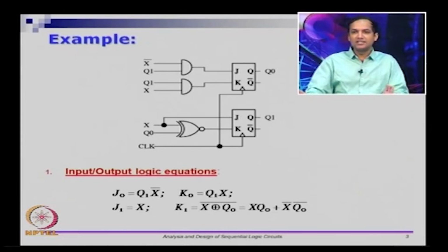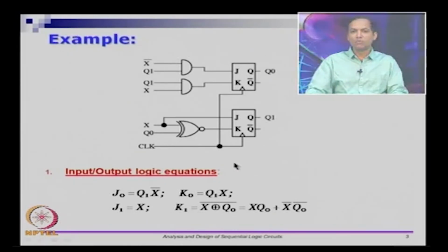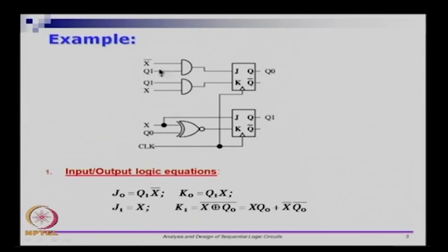So it is a valid synchronous sequential circuit, and from the canonical model, the only thing that has degenerated here is that there is no output logic explicitly, right. And to be more specific, since the output is Q1 Q0 explicitly, it is only the flip flops that are controlling the output. So this is actually a Moore machine. I mentioned this in the last video. This is actually a Moore machine where the output depends only on the states but not on the inputs directly. So this is a Moore machine. Now I want to find out what the state diagram for this is.